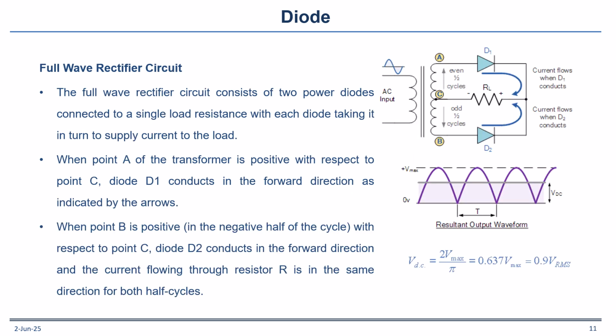If we want to make it much better, we can make a full-wave rectifier circuit. We can put one diode here and another diode here, and it works like this: when we have positive polarity, it goes from here, and when we have negative polarity, it goes from here. So the resistor sees something like this. But again, we have a lot of oscillations.